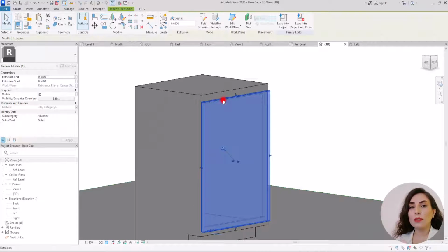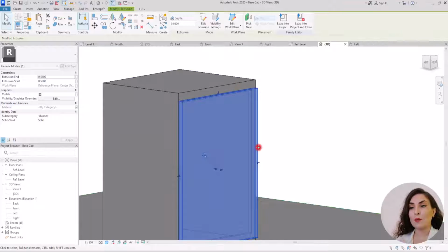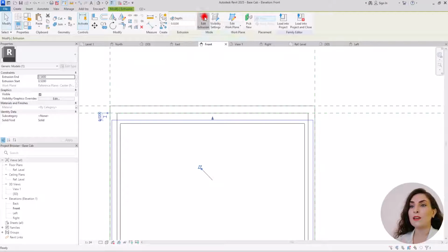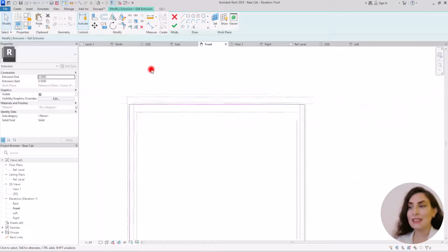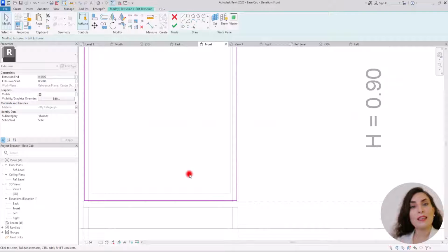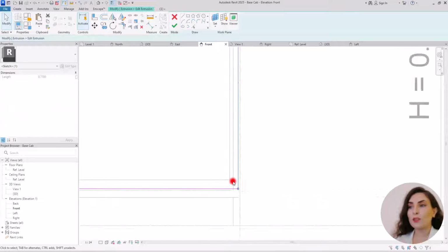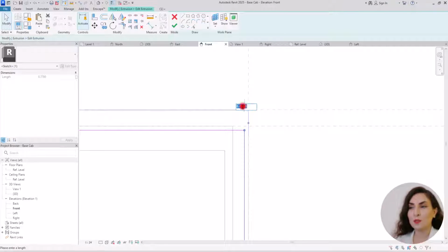So for the door in here, I don't want to see this gap in this part. I want it to be on the other side. So we can go to the front view, and in here I can put it back on exactly 5 mm like this, and then we can create the gap from this part. So I want this part to be maybe 1 to 2 centimeter. Let's go with 15 mm for now.